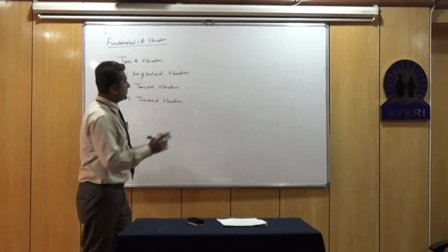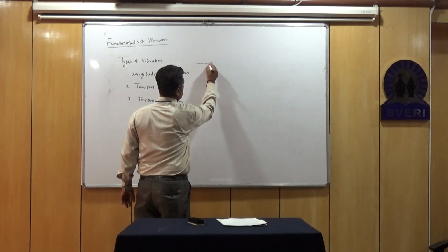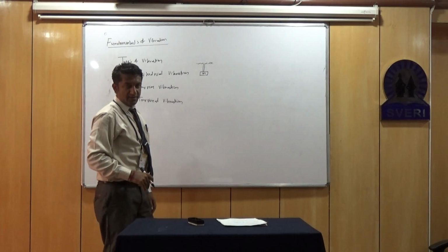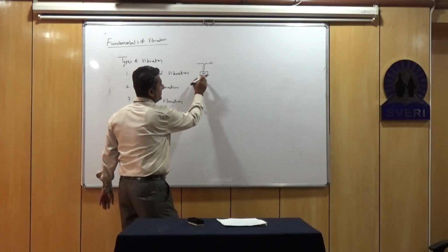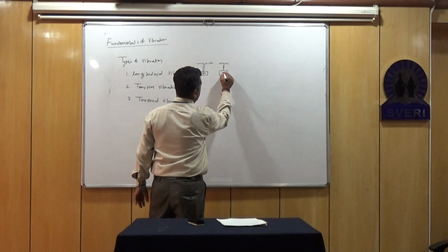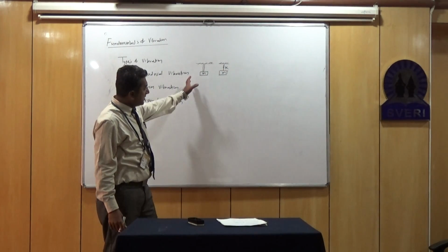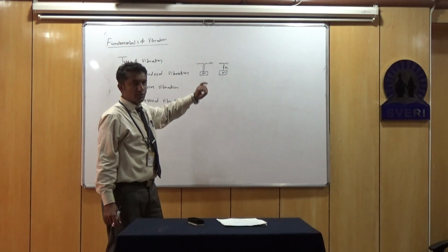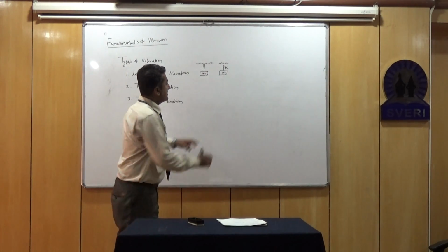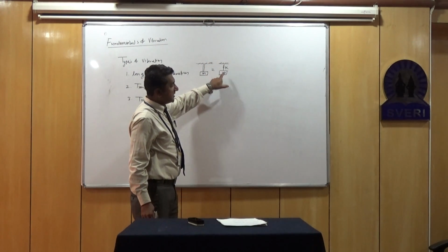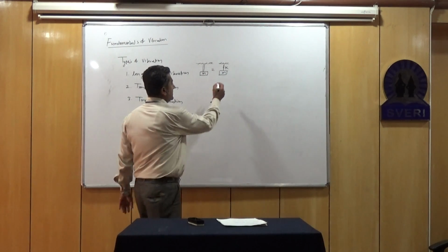Now when we are going to see the longitudinal vibration, let me draw here a simple diagram of any vibrating system. Suppose this is a mass which is connected by means of this wire or any rod. At that time this can be replaced for the mathematical modeling, so that all stiffness we can put as a spring, and all mass, that is including the mass of this shaft as well as this mass which has been hung by means of one rigid support, can be replaced by this equivalent system. That is, we are going to say all stiffness is converted into spring and all mass is concentrated at a certain mass level M. So when it is vibrating,